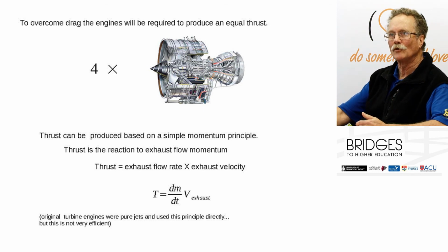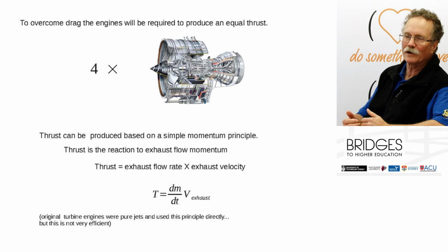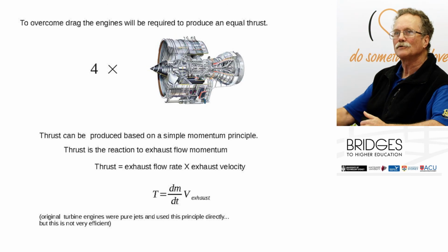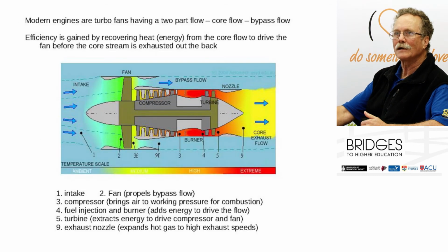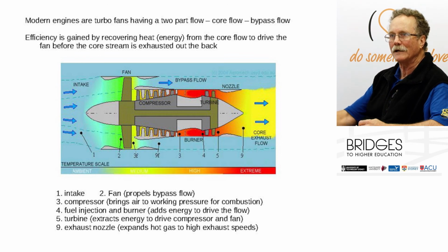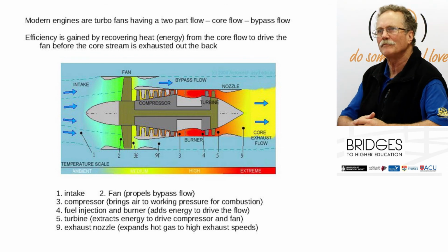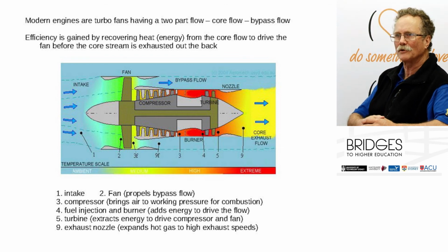If you have three or four, it's like gears in your car. It's not efficient to have 2 gears. It's much more efficient to have 5 gears. So more development in that area, in the mechanics of the inside of the engine to reduce mechanical inefficiency. And again, the most development is going on with these fans to make them lighter, improve flow quality and make the bypass flow bigger. So bigger than even 11 to 1, maybe 12, 13 to 1 bypass ratios.